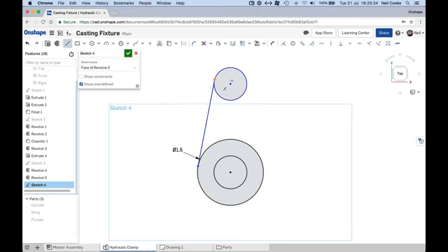And very simply, just drawing on here, you can see it's picking up a constraint and a tangent. You can also then pick up or highlight some of these other ones, so you can see I've made something horizontal to that and coincident to that and tangent over here. So very quickly you can start to draw and add these constraints.